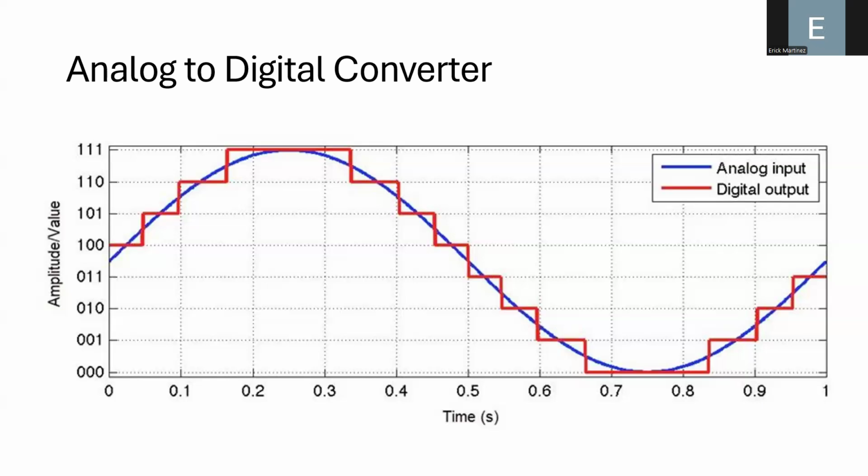And real time is not about the fastest processor. It's about executing code always at a deterministic time. We always want to take data with a deterministic behavior because that ensures that we correctly sample all the important dynamics of the sensor. We cannot take samples arbitrarily. That will be a problem, and you will obtain very strange dynamics.